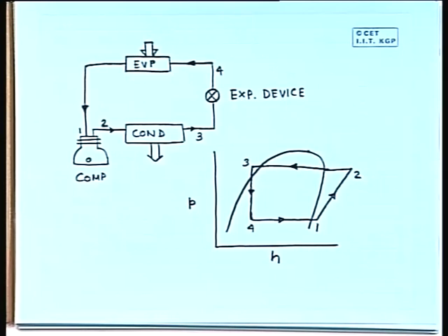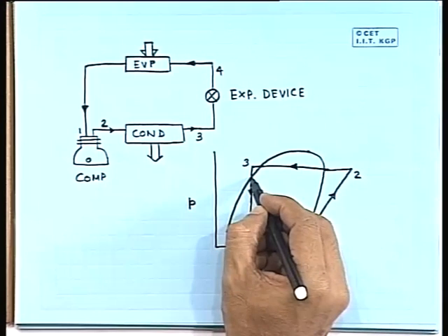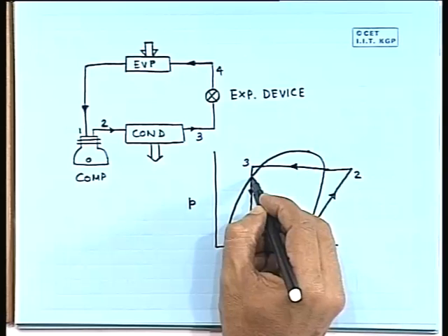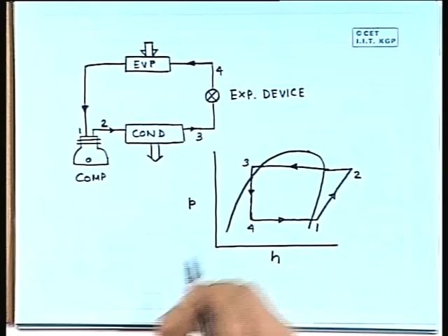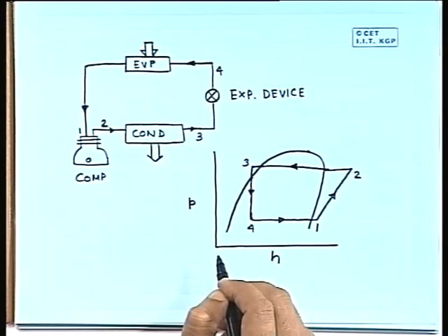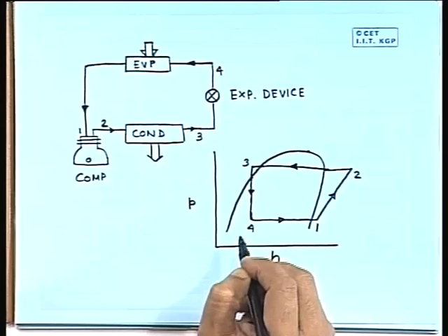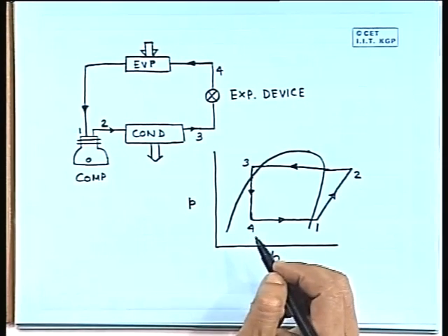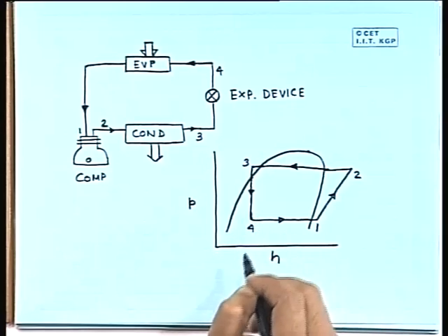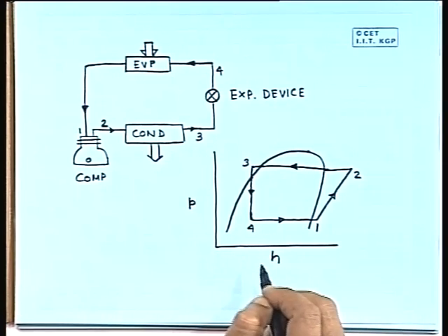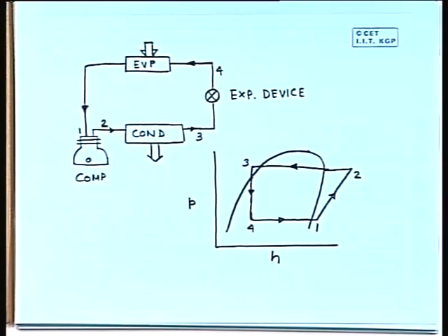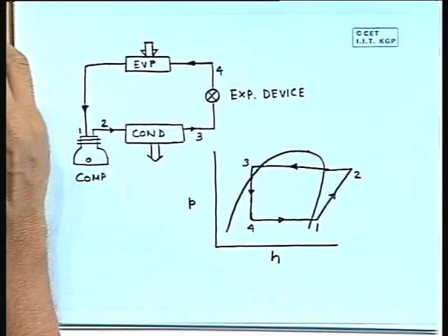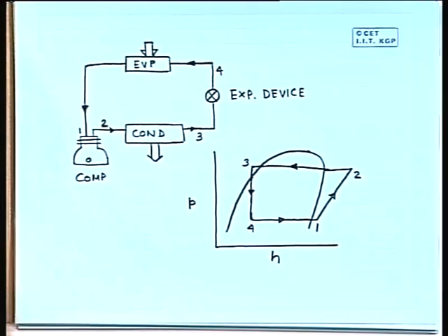You can see that this is starting from almost saturated liquid, but as it goes in the downward direction, as its pressure reduces, more and more vapor generates. This is some kind of a flashing process. So, we will have more and more generation of vapor, and obviously the process is complex and a lot of irreversibilities are involved with it.